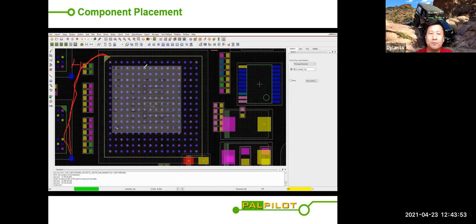Okay. And your PCB, like a sandwich, should be symmetrical. So it usually is an even number of layers: either 2 layer, 4 layer, 6 layer, 8 layer, 10 layer, 12 layer. So if you add 1 layer, guess what? You're not adding 1, you're adding 2. Okay. And when you have more drills, that costs money at the fabricator as well.